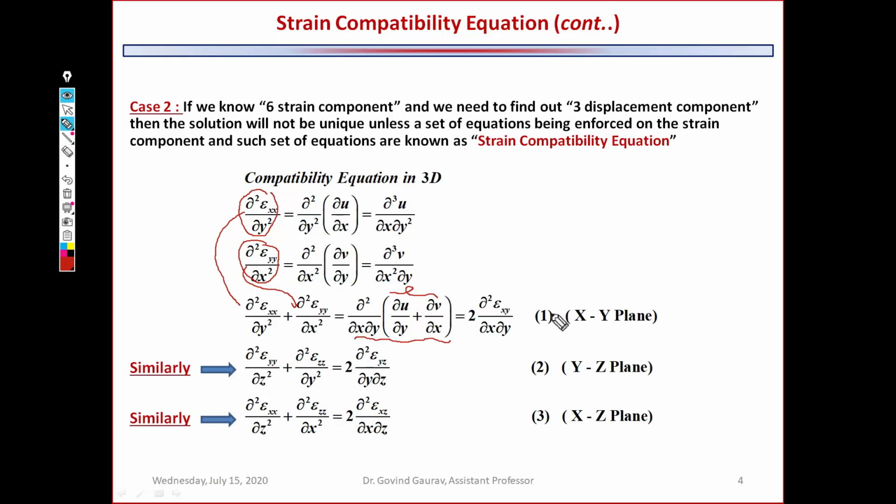So this one is the first strain compatibility equation in the xy plane. If we carry out similar formulations to what we did for the xy plane, for the yz plane, we will arrive at this strain compatibility equation, which is in the yz plane. And similarly, if we carry out the similar formulations, we will again get a strain compatibility equation that is in the xz plane.